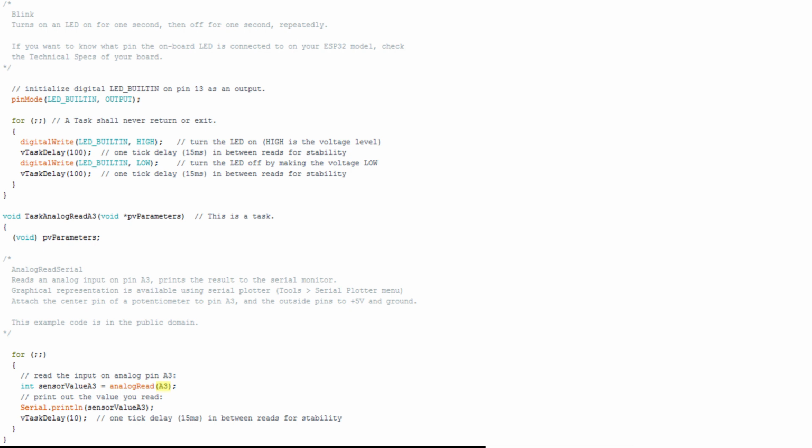An analog value is something that is not digital in origin, such as the output from a potentiometer that can have an infinite set of values between two positions as it is turned. The range of an ADC is limited by its number of bits. With an ESP32, the range is from 0 to 4095. This is because the integrated ADCs are 12-bit.